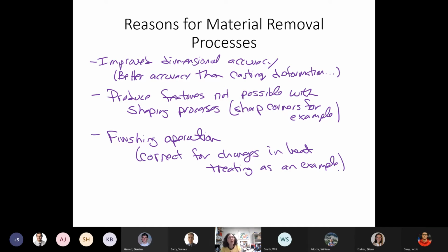Because you have this uneven heating and, more importantly, uneven cooling, you will get dimensional changes. A lot of times that shows up as distortion, and it also can show up as residual stresses. So residual stresses and distortion are different sides of the same concern or issue, which is uneven cooling, and therefore uneven thermal contraction.